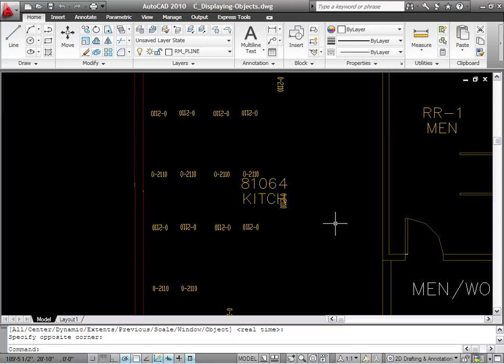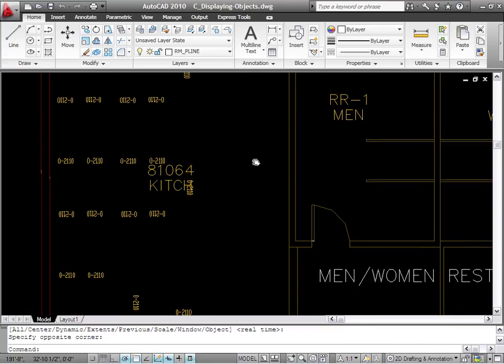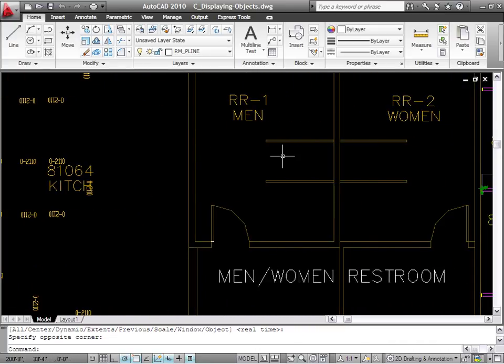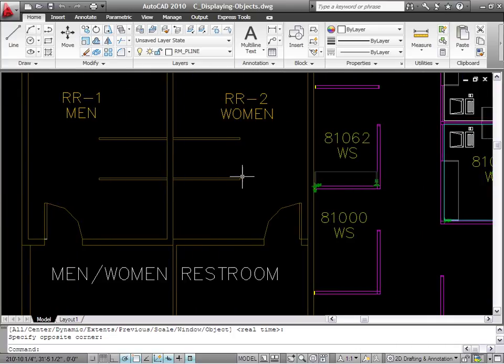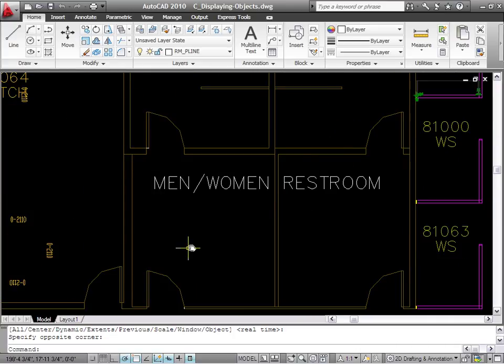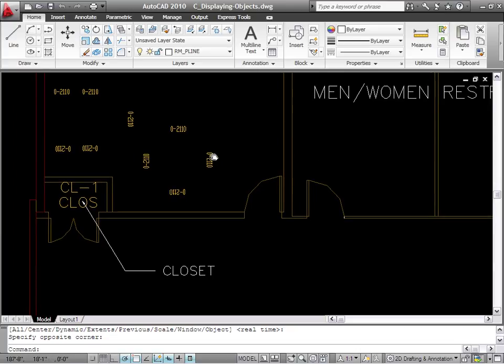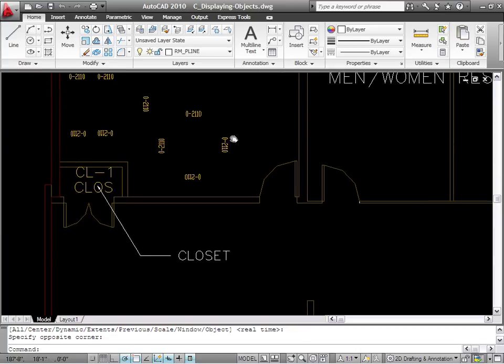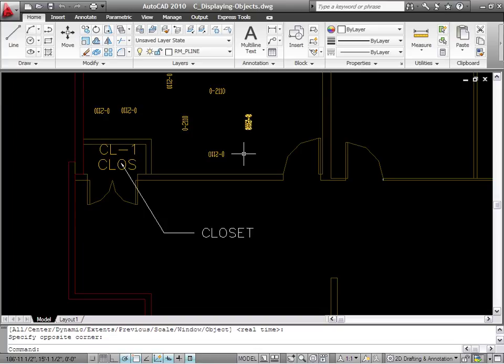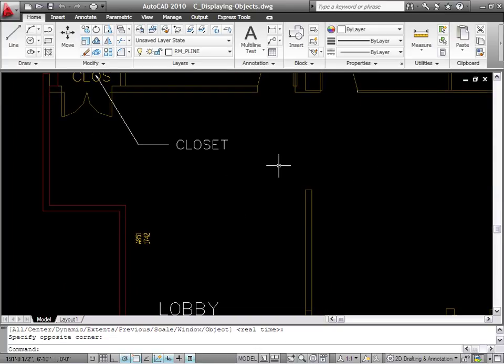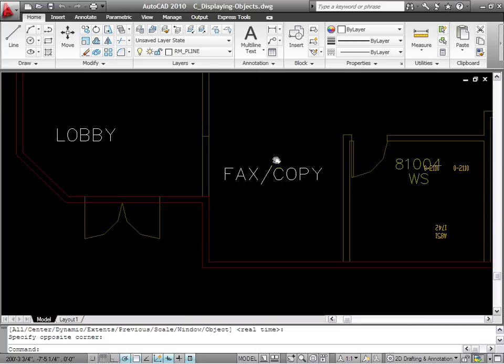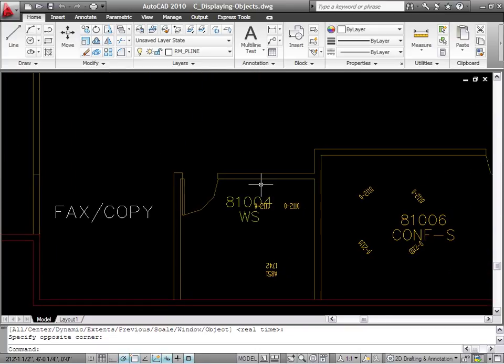So if I want to move around the drawing, the shortcut would be to hold on your roller mouse. If you hold your roller mouse and push to the right hand side, you can pan around the drawing. This is called pan. When you click the roller mouse, it will show the hand picture. This is the pan picture. So if you are done with the pan and moving around the drawing, maybe you want to take a look back at the whole picture of the drawing.